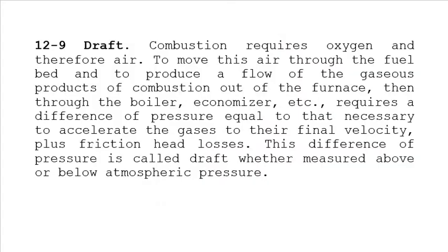So draft. Combustion requires oxygen and therefore air. To move this air through the fuel bed and to produce a flow of the gaseous products of combustion out of the furnace, then through the boiler, economizer, and etc., requires a difference of pressure equal to that necessary to accelerate the gases to their final velocity plus friction head losses. This difference of pressure is called the draft, whether measured above or below atmospheric pressure. So draft is the difference of pressure. That is what we call draft.